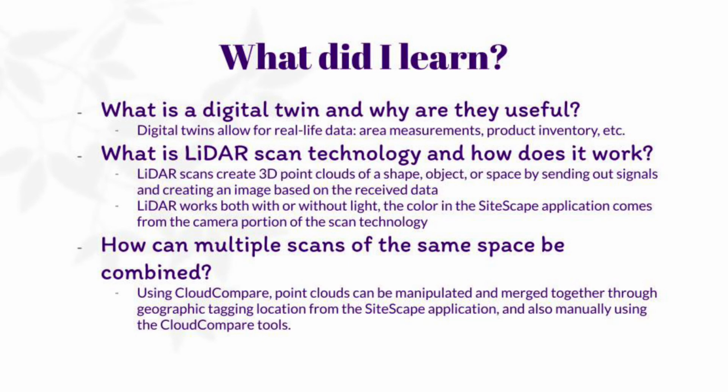How can multiple scans of the same space be combined? Using Cloud Compare, point clouds can be manipulated and merged together through the geographic tagging location from the Sitescape application and also manually using the Cloud Compare tools.